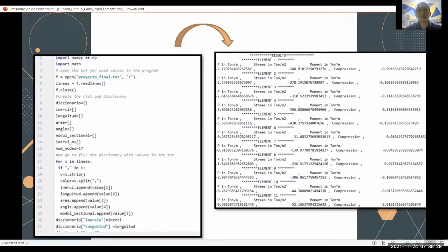Having obtained the initial conditions of force and moment of the structure, we find the displacement matrix that Excel gives, used to get the stress for each element and the moment, using the local displacement, and check if the maximal stress is within the DNV range.